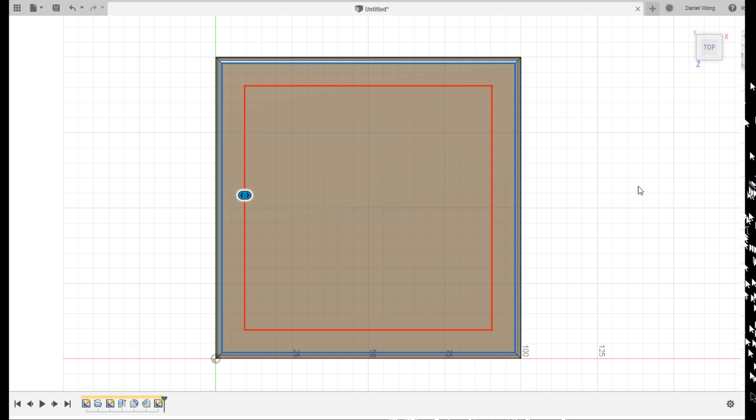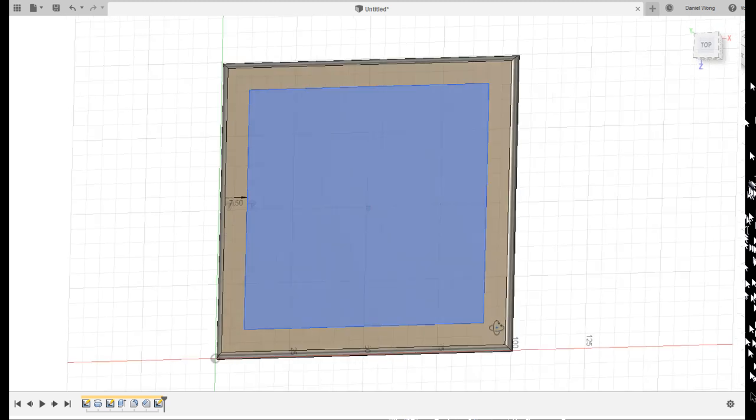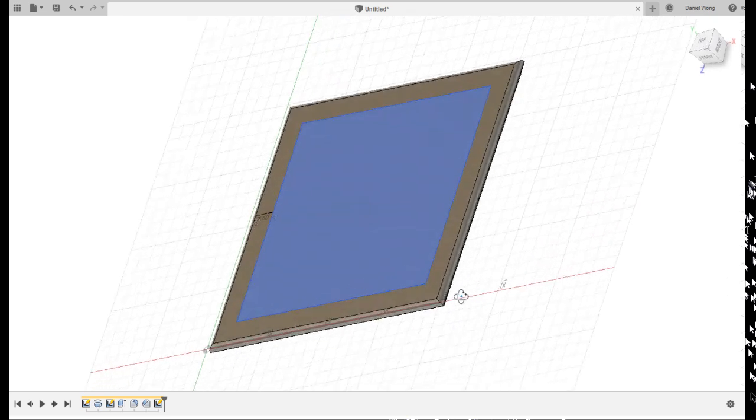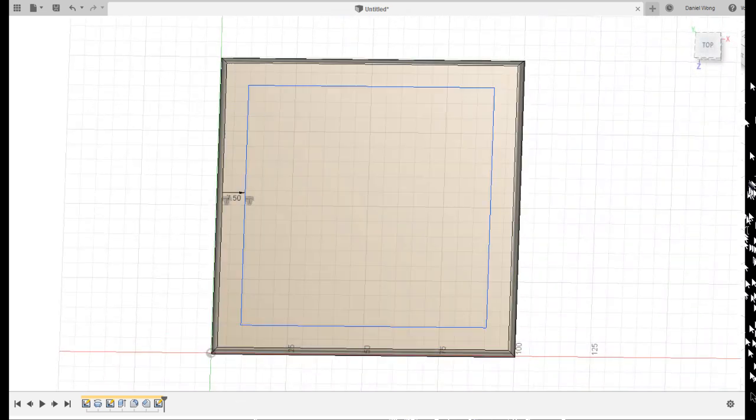So our rail is going to be quite thick there, right? Past 7.5mm, we're going to recess that. So if you press OK, give us a moment. There we go, we've got a rectangle there. You'll notice that it's blue, but the way this has been defined is with respect to the outside boundary, so you don't need to worry too much.